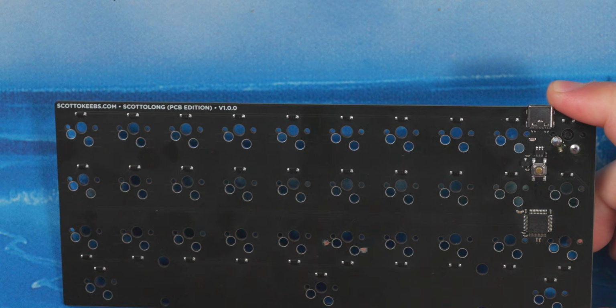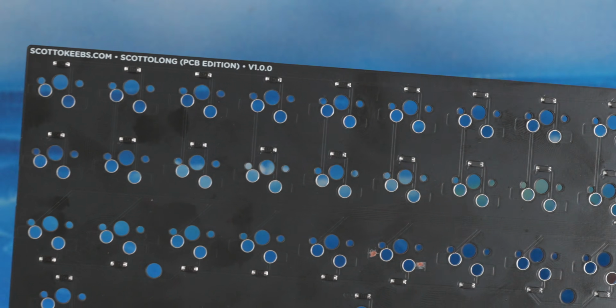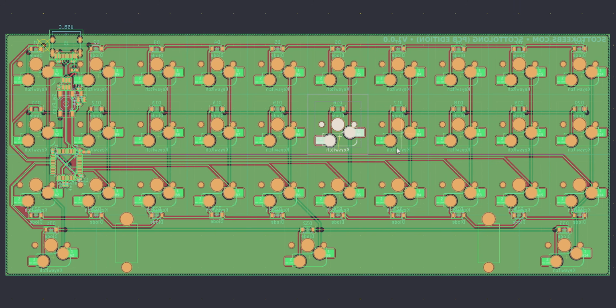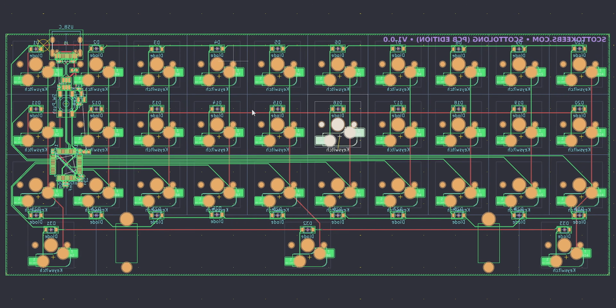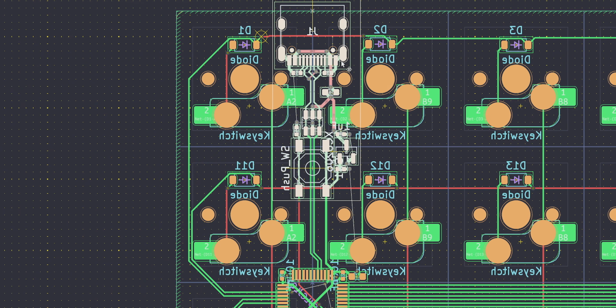And what I'd actually like to do is take a look at this so you can kind of get an idea how that looks too in software. So we're going to jump into KiCad yet again, just take a quick look at this physical PCB in the KiCad software, see how that looks, and then we'll take a look at ordering them. So what I'm going to do first here is I'm actually just going to press Control B to unfill the zone. And you can see how this works is that we have our little module for the USB here.